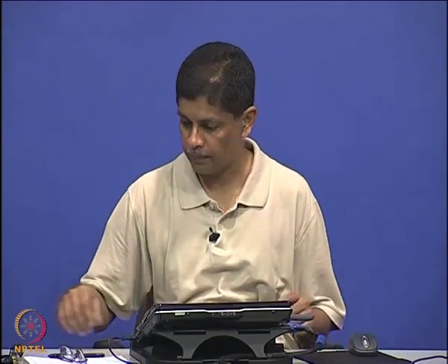So, today we basically discussed the Viterbi decoding algorithm, and I carried through an example using our example trellis, and I showed you how the Viterbi decoder reduces complexity by being able to identify, if you think of decoding as choosing the winning path, losers early enough so that you do not spend a lot of time with the losing paths and are able to quickly identify the winning code word that is closest to the received vector. So, next time we will continue our discussion on convolutional codes. Thank you.